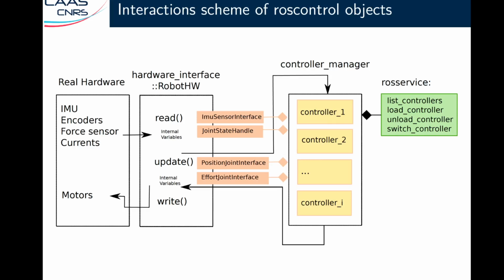And this update will call a set of controllers which will interact with the hardware interface through the API that I described previously, which means the IMU sensor interface, the position joint interface, or the effort joint interface.